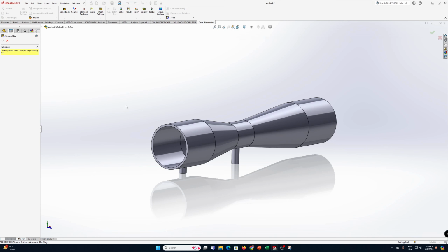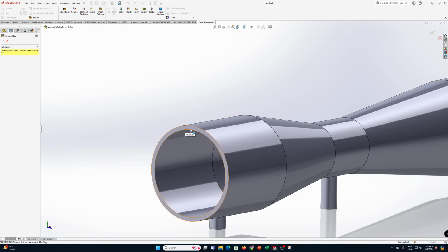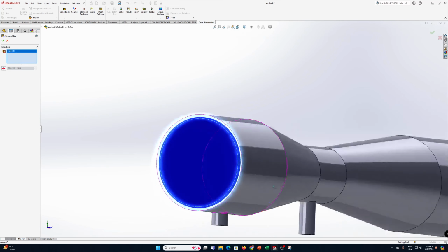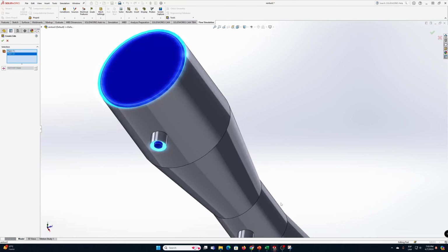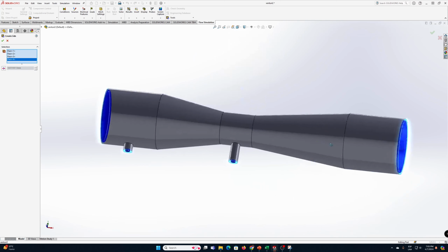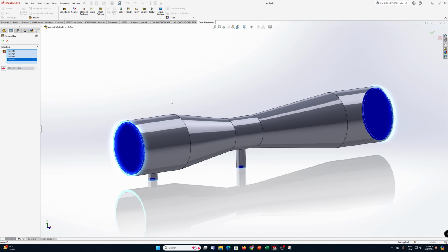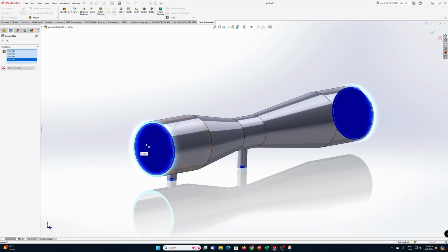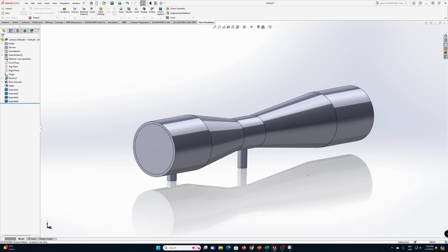And the only thing you need to do is select a planar face that is already set here. Select the planar faces the openings belong to. So select in this option, this one, this, and this. So we have 4 faces. And you will notice now there is a blue color here that represents the lead. So now I will select OK.